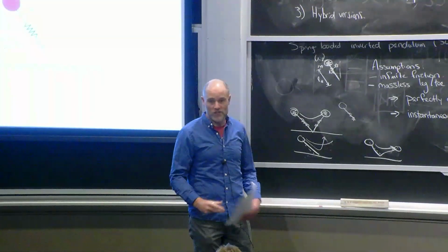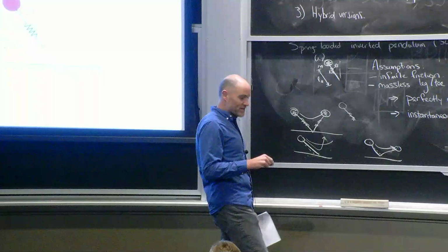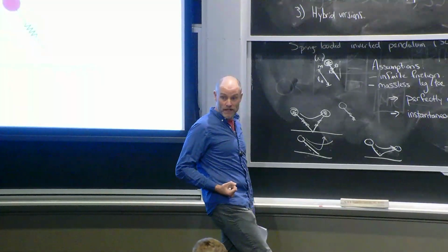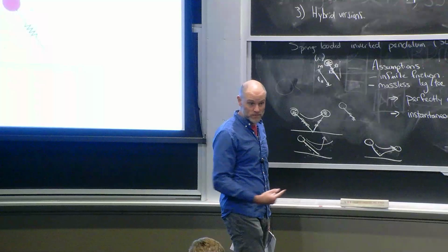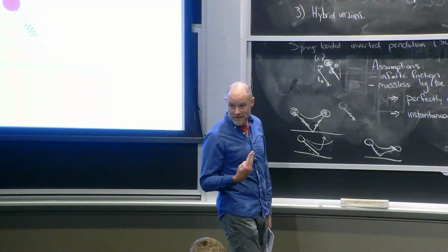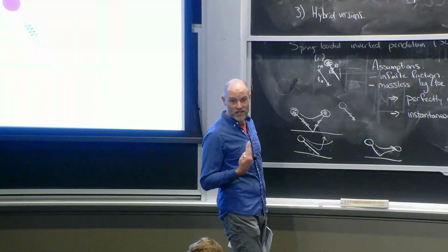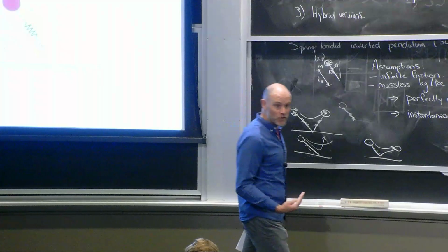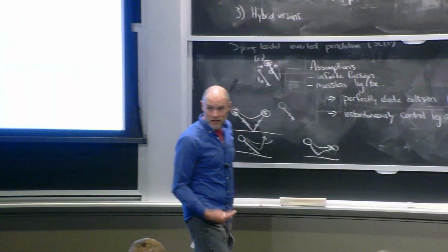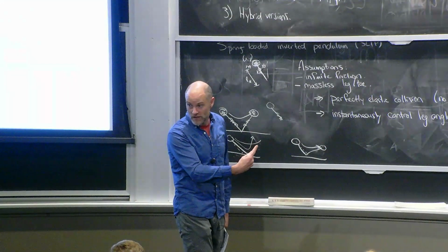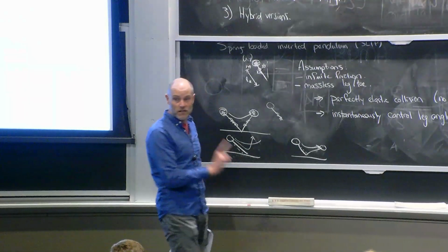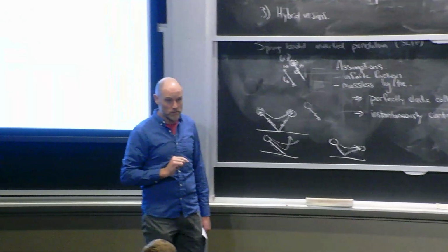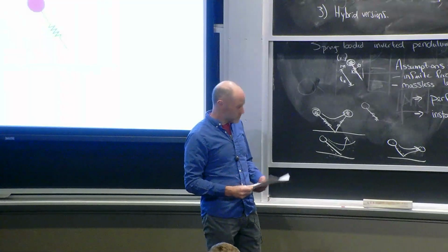It's limited in the sense that at the moment of being at the apex, you have to decide basically everything you're going to do over the cycle. Your feedback, your decisions are made only based on the state at the top. If something happened to you in the middle of your hop, you're not going to respond to it until you got to the next one. You've only made one control decision per hop. But in that case, the Poincare map tells you everything you need. Okay.